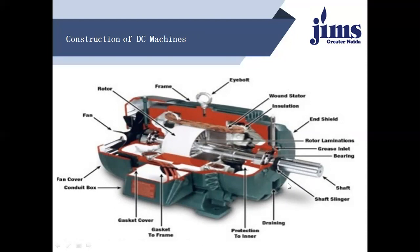Then there is an end seal. There is insulation provided over the entire machine. In the case of the rotor, there is rotor insulation. Over the stator, there is stator insulation. The stator insulation is quite lower as compared to the rotor insulation, because the stator is stable and there is no movement. But in the case of the rotor part, there is movement because the rotor rotates in a specific direction.